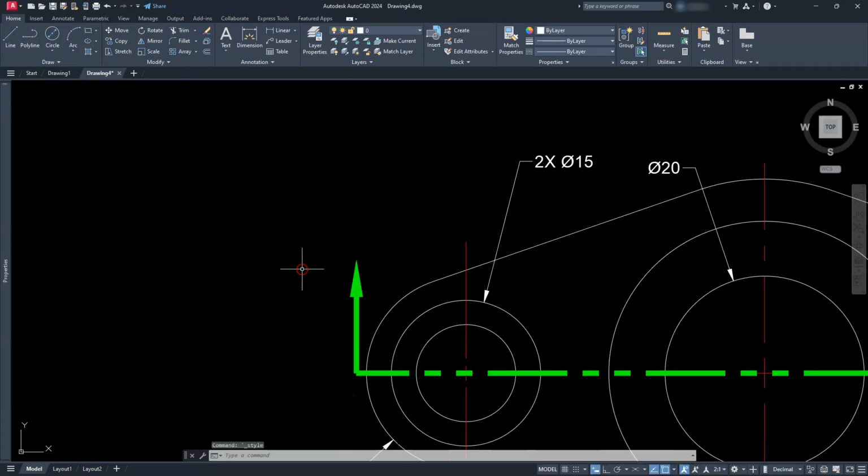The major difference that you're going to see is that when I use the single line text, it's going to ask me for a point, right? I'll go ahead and tell it I want to use the bottom center, so I'll type in BC here, and that's going to tell it to give me a bottom center start point. I'll click right along this endpoint, and then it's going to ask me what's the paper height, right? So it's going to do the math for me.